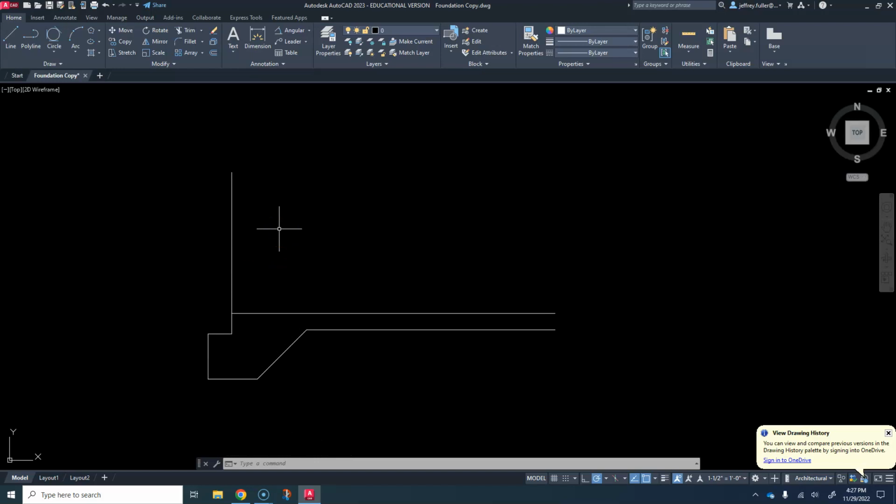And I want to offset this line because what this is representing is the core material of my wall, the 2x4 lumber that my wall is made out of. Remember this because your life depends on it. A 2x4 is not 2 inches by 4 inches. It is 1.5 inches by 3.5 inches.